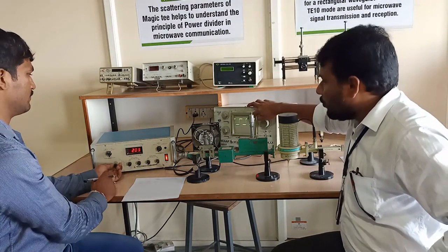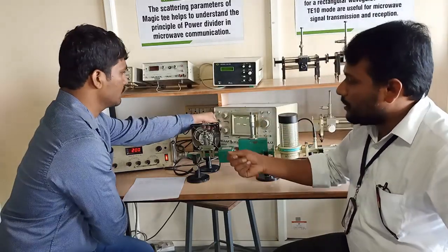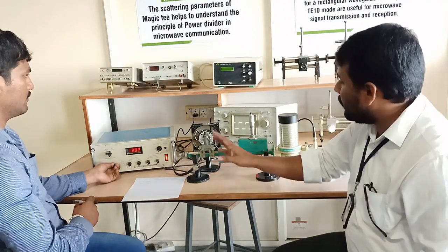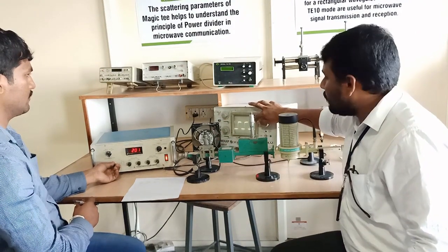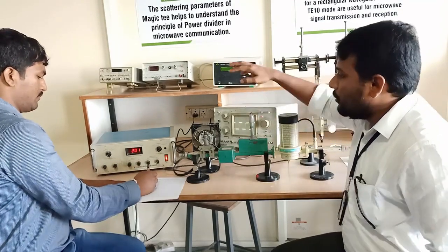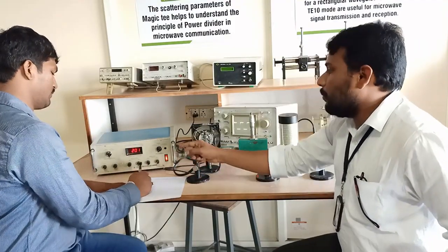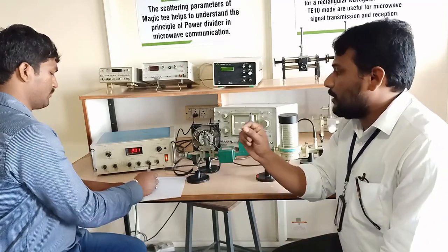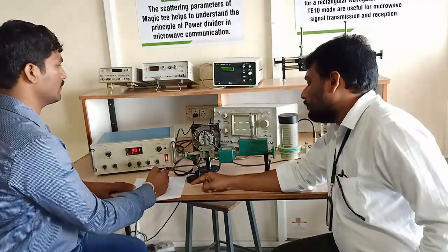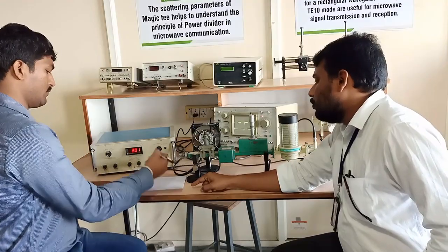Now, by rotating the Repeller voltage knob in the anti-clockwise direction, check where you get the maximum signal. You have to verify it by rotating the Repeller voltage knob completely. Wherever you find the maximum signal strength on the CRO, fix that voltage. Now we are taking 201 as the Repeller voltage, and keep a minus sign because it is a reverse voltage. So the Repeller voltage is minus 201.